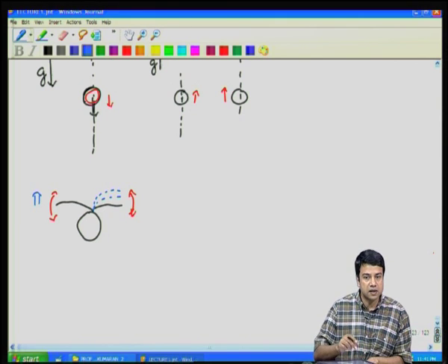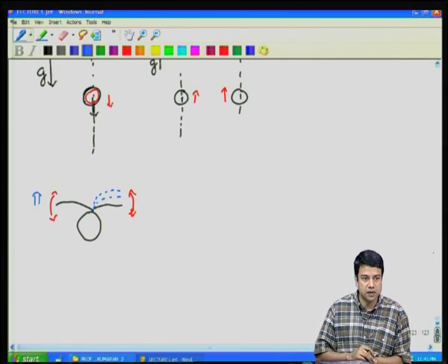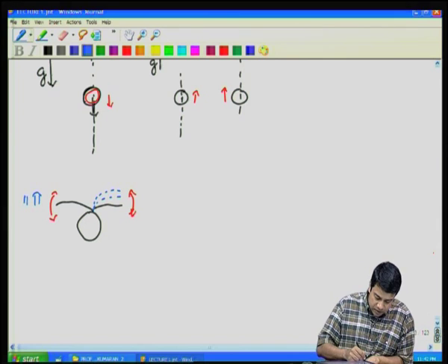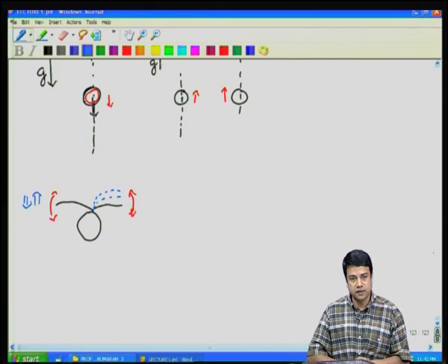Note that the velocity at an instant in time only depends upon the velocity on boundaries at that instant in time, in this particular case on this moving object at that particular time. So, the velocity at each point in the boundary is reversed between the upstroke and the downstroke. That means the velocity within the fluid at each point is also reversed. Therefore, if this microorganism moves a certain distance along the upstroke, if the downstroke is exactly the reverse of the upstroke, it has to move an equal and opposite distance on the downstroke.